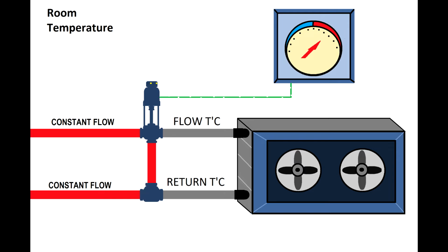You can use a system that stops the fan, but if you keep the fan running, it will be good for destratification. So in this case, the fan will not stop, only the heating agent will be restricted, and the heating will be held off by the thermostat until the temperature goes below the set point.